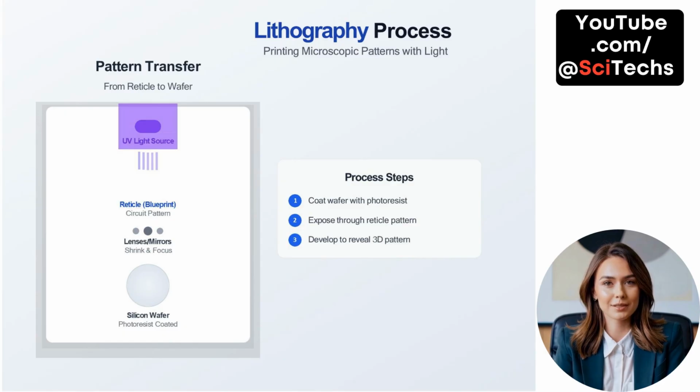Pattern transfer, from reticle to wafer. The lithography process involves transferring a microscopic circuit pattern from a reticle or blueprint onto a silicon wafer using ultraviolet light. The first step is to coat the wafer with a light-sensitive material called photoresist. This coating is essential because it reacts to light, allowing for selective patterning.